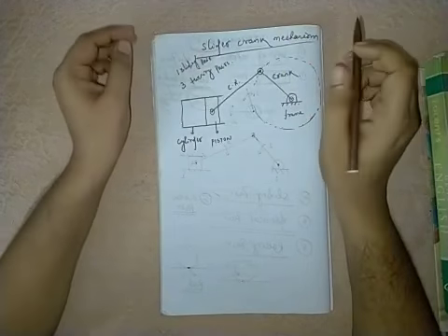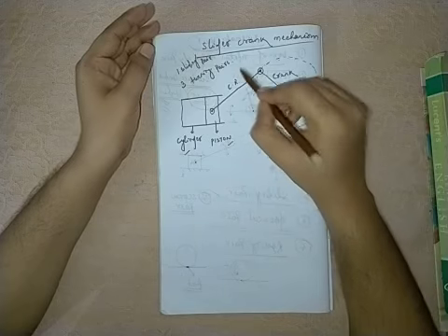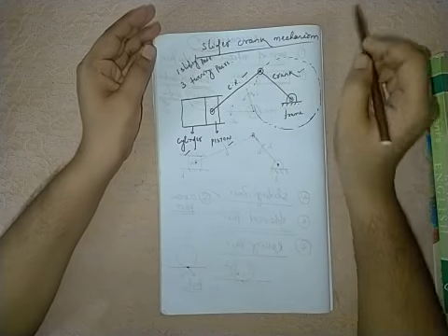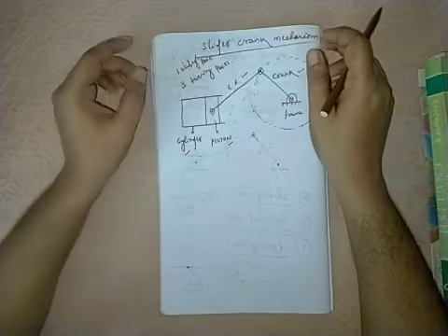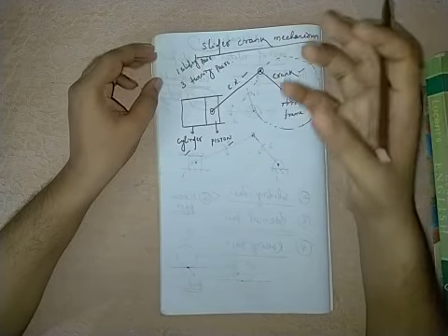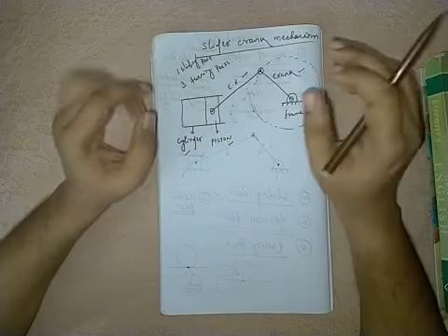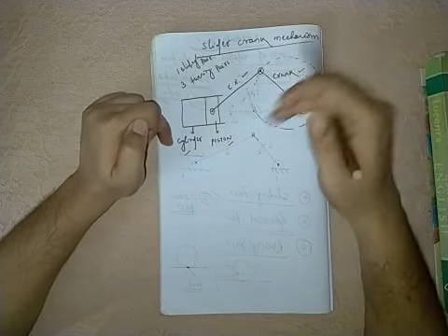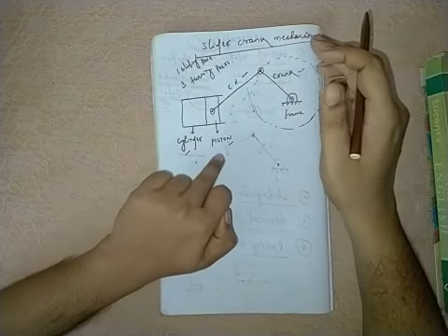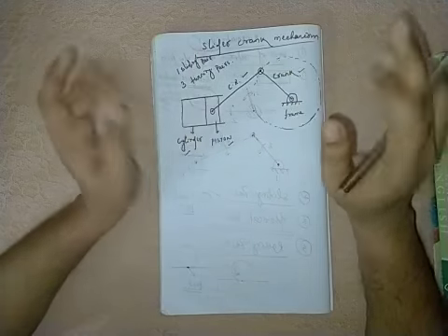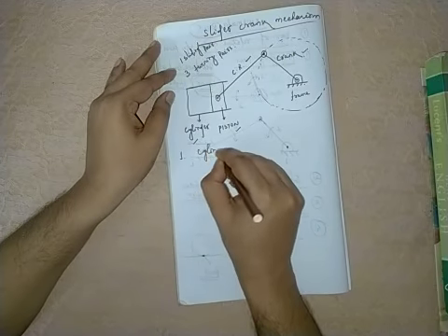There are basically four parts: cylinder, piston, connecting rod and crank. Inversion means we will fix different parts and check what output the machine will give. First we will fix the cylinder and see which type of motions or machines we can get. Next we will fix the piston, and similarly the connecting rod and crank. So let's do first when the cylinder is fixed.